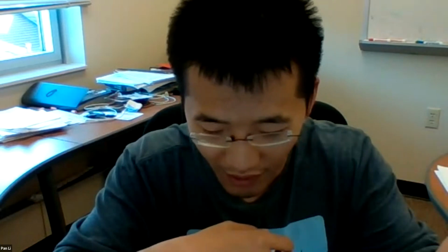Yeah, because it's time to close our meeting, but I have a few questions regarding the AI for IC part. You can ask. I was wondering, for placement, which is a combinatorial problem, do you think the objective function we want to have is more like a white box or a black box? For example, if I want to predict latency, I think the current wire length is just theoretically designed, not some ground truth, right?